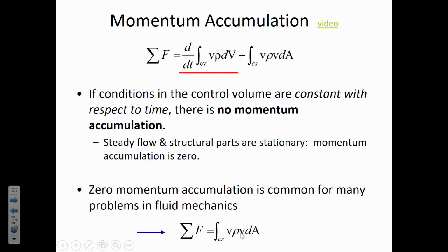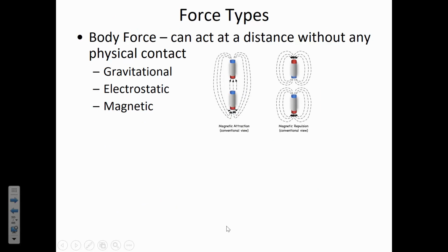There may be multiple streams that we have to keep track of, and that's what kind of makes it tricky, is that there's a convention for the direction of the jet, and there's also a convention that we'll have to ask ourselves if the stream is going in or out of the control volume.